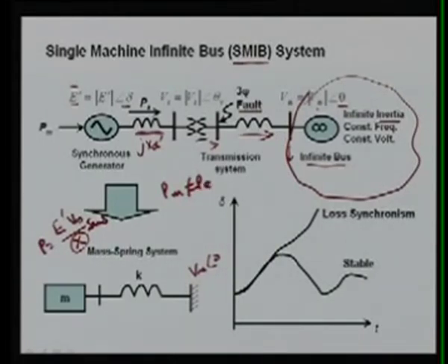So to make it, what will happen? This Pe, this delta will keep on increasing. Because this value is larger, if it is to maintain this Pe constant, this delta will increase, and now you can say delta is increasing. So over the time period during the fault, this delta can follow different trajectories.